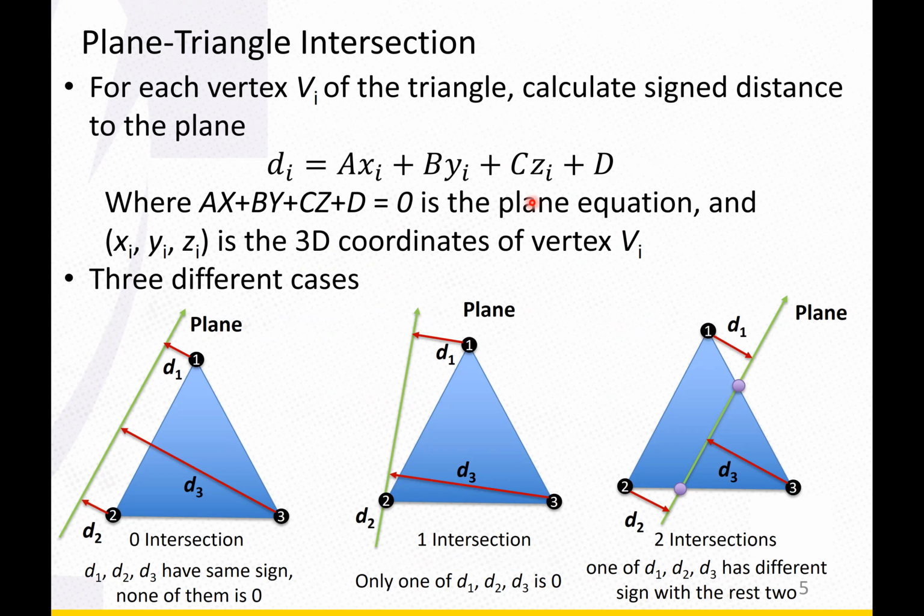But still, if the triangle quality is really bad, because what we're showing here, all the triangles are near to regular triangles, meaning each angle is similar to 60 degrees. But if you imagine you have very narrow triangles or very flat triangles, that will really cause problems when you do the computation. For example, if you are computing an intersection between the plane and a very small edge, you can imagine how unstable it is. So all these problems will make the computation fail.